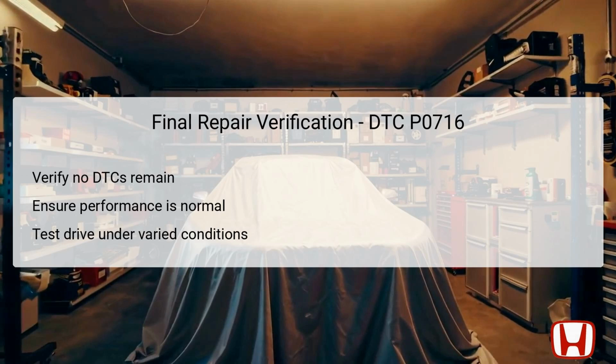In the final repair verification stage, it is critical to confirm that no DTCs remain after completing all necessary repairs or adjustments. Utilize the HDS to scan the system thoroughly, ensuring that it does not indicate any residual error codes connected to the speed sensor circuits.